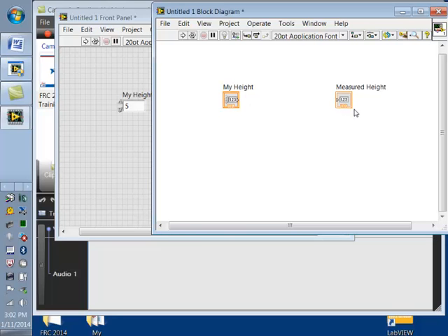How do I do it? Where do you think the number comes out? At that triangle, right? So I float over that triangle. Notice my cursor changes to a spool of thread, and I click. Notice I think right-clicking is so important that when I mean right-click, I will say right-click. But clicking just means left-click, right? So I left-click, okay, so I click, and I can make a wire.